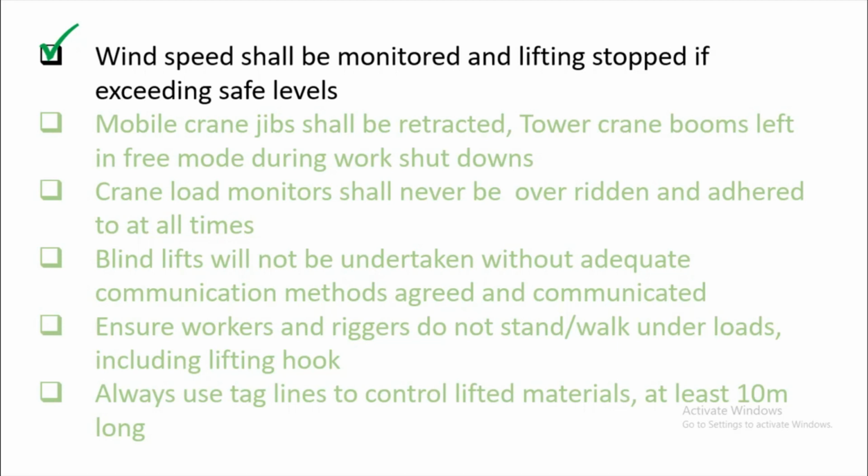You cannot rely on only one location to check the wind speed. So always check the maximum wind speed or safe operating speed of your crane, and also the maximum wind speed that legislation or regulations require, so that you are not violating the rules.